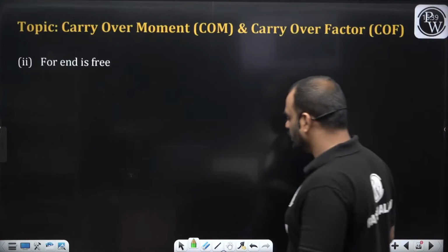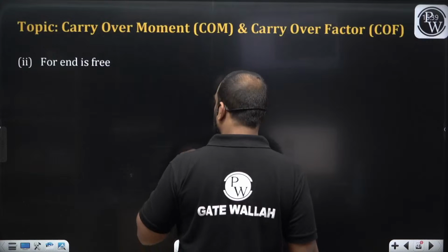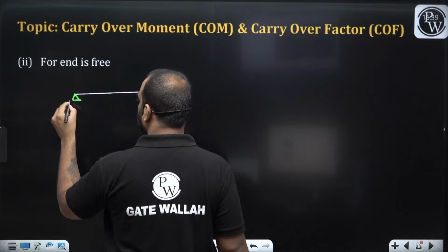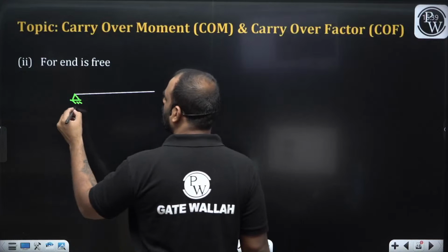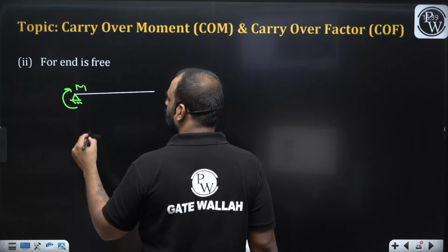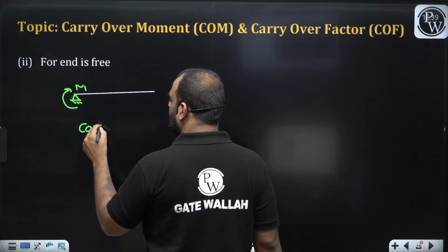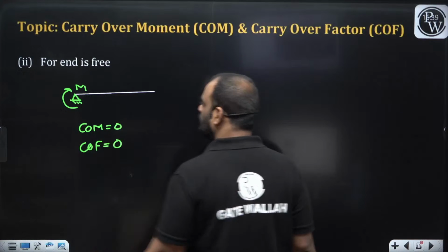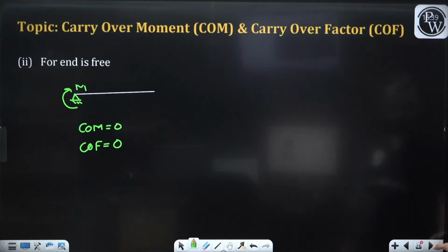Now when far end is free, what will happen? When far end is free, very simple. This particular end is not capable to bear any moment. So the carryover moment value is equal to how much? 0. Similarly, carryover factor is how much? It is also 0.